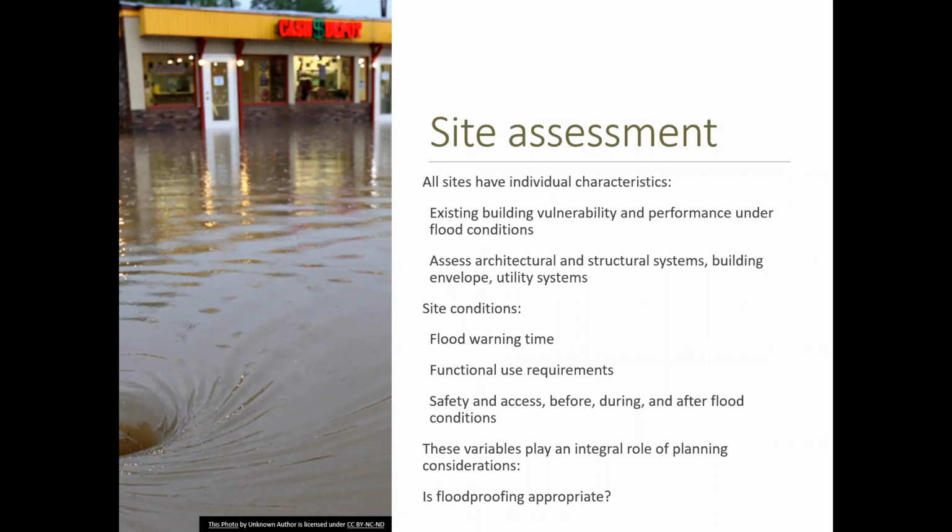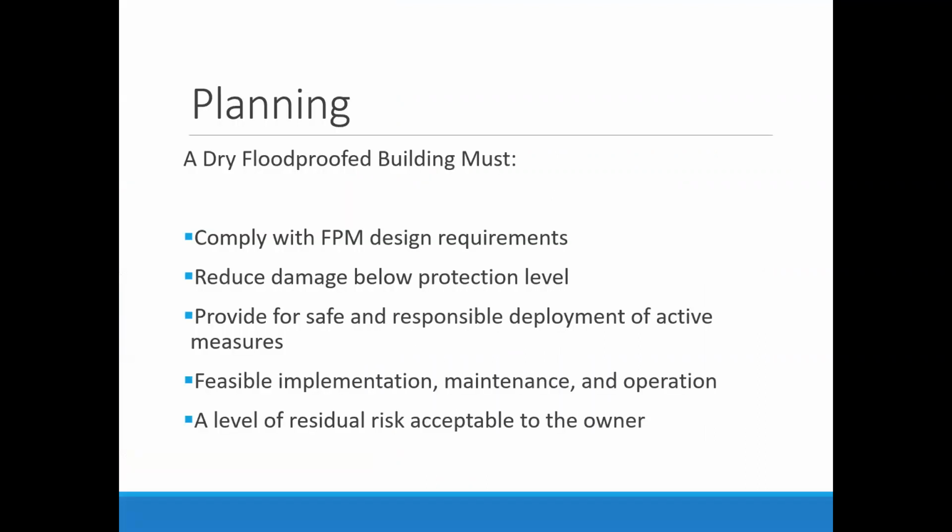And utilities, we have to floodproof them somehow. Elevating would be the best thing, but you can build them their own enclosures, or you can make sure that they're designed to be submerged or something like that. And then we'll get into the required plans. This is based on the new Dry Floodproofing Technical Bulletin 3 that was released, I think last year sometime, 2021, so pretty recently.